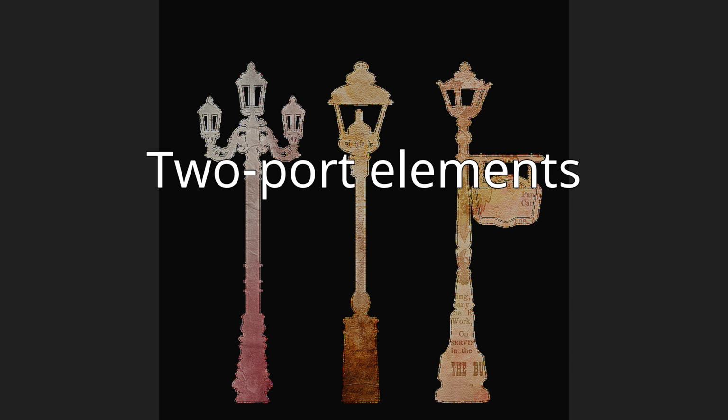The transformer maps a voltage at one port to a voltage at the other in a ratio of n. The current between the same two ports is mapped by 1/n. The gyrator, on the other hand, maps a voltage at one port to a current at the other. Likewise, currents are mapped to voltages. The quantity R in the matrix is in units of resistance. The gyrator is a necessary element in analysis because it is not reciprocal. Networks built from the basic linear elements only are obliged to be reciprocal and so cannot be used by themselves to represent a non-reciprocal system.